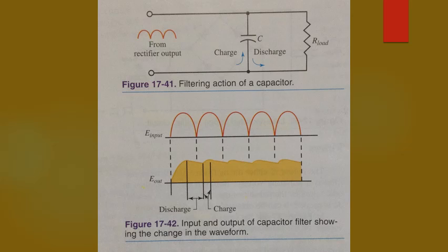Capacitors used for this purpose are electrolytic types because large capacitances are needed in a limited space. Common values for the capacitors range from 4 to 2000 microfarads. Working voltages of capacitors should be in excess of the peak voltage from the rectifier.